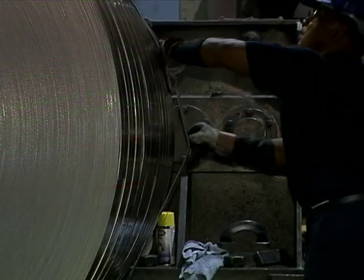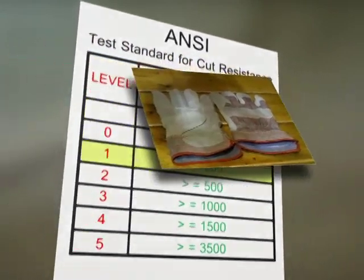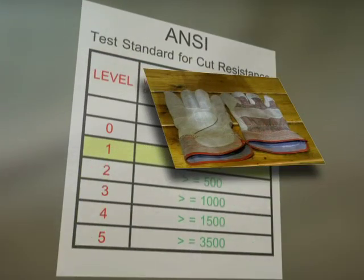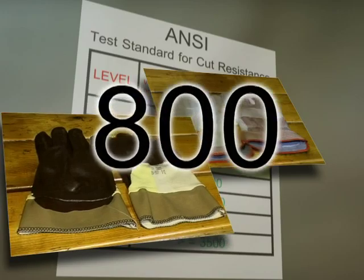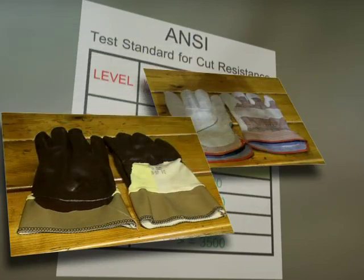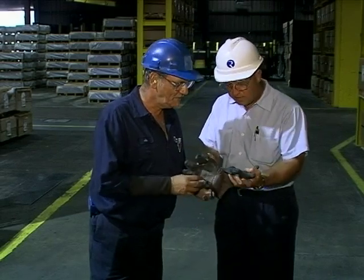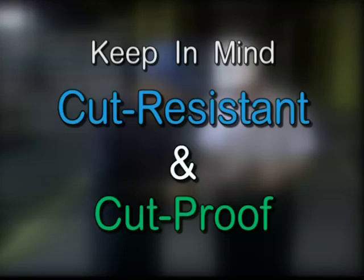A common misconception is that leather gloves are cut resistant because they are thick and bulky. The average cut resistance for a leather palm glove is less than 300 grams, which is only a level 1 rating. This Medalist foam Kevlar-based glove has a cut resistance of 800 grams, providing almost 3 times more cut protection than the thicker leather palm gloves. Your supervisor will be able to inform you of the proper gloves you need to wear for your specific tasks. Keep in mind, there is a difference between gloves being cut-resistant and cut-proof.